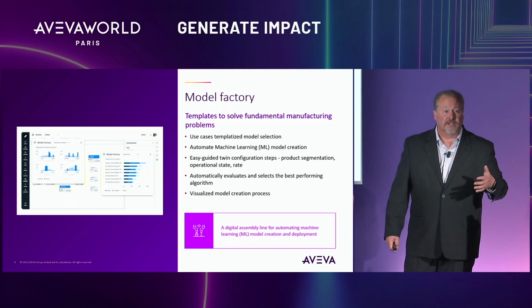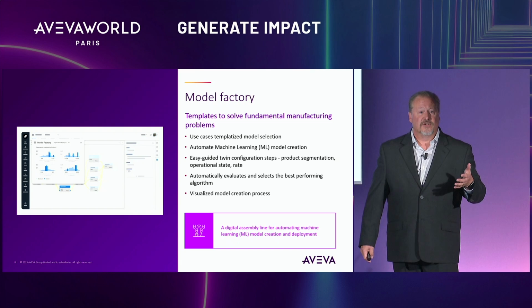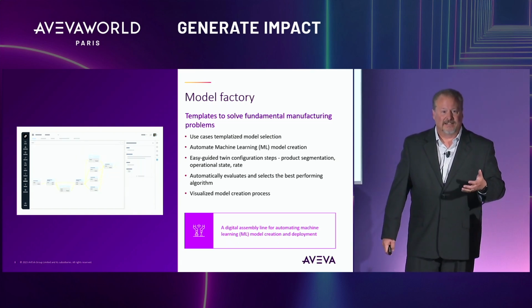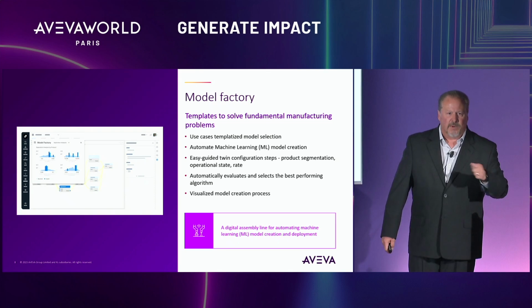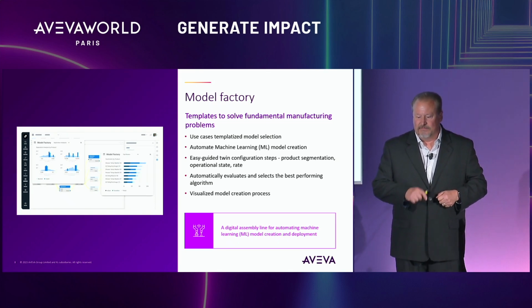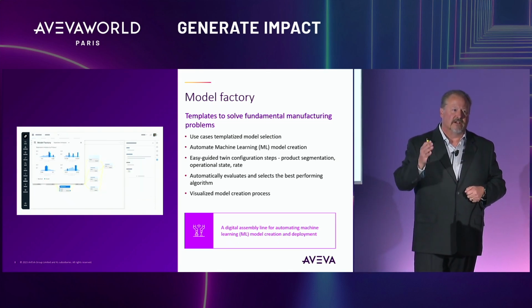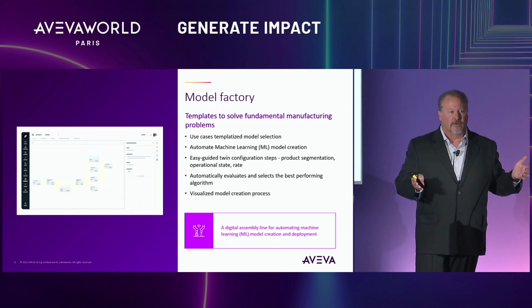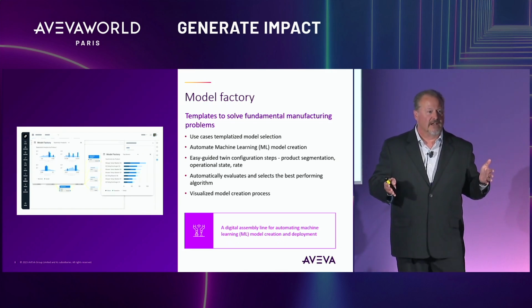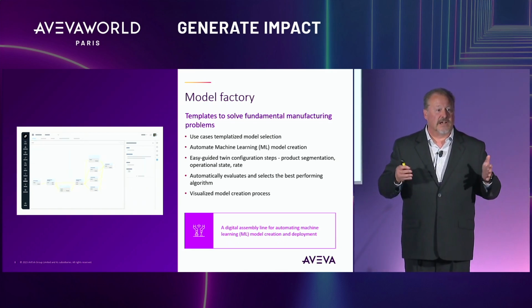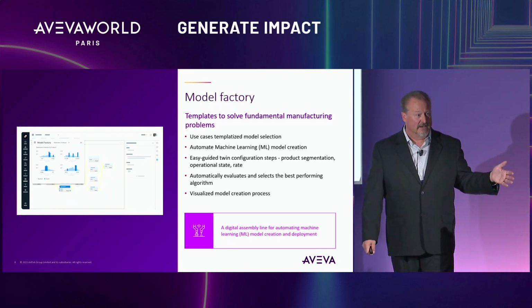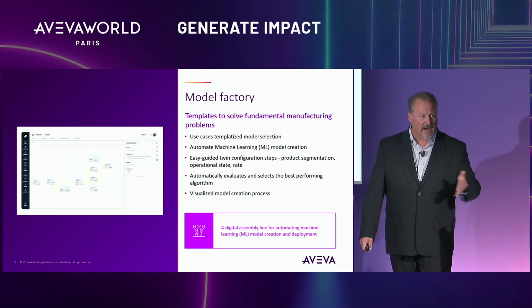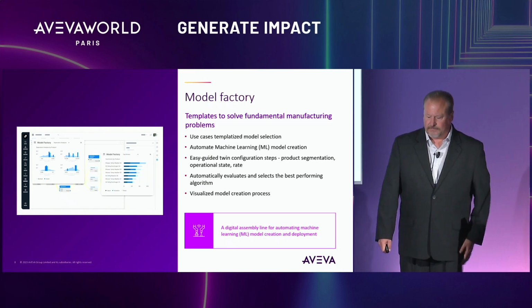And you simply go into your Connect Data Services streams or assets with the metadata and pick the data that you want, make it part of the model, and walk it through the wizards, and it'll start to train the model going back as far back as you want. Typically, this is going to be several months or even years of data that you may want to look back in history to look for anomalies and look for patterns.